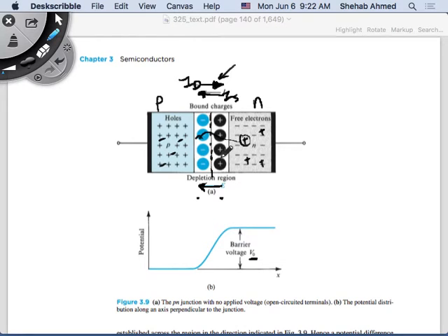And the potential difference. And hence, here positive bound charges, here negative bound charges. If you have two regions with a difference in charge, and an insulating medium between them, it's like having a capacitor. So basically, this graph is showing you when they're joining each other, that's the curve, and then when they're fully joined. Which graph? This curve. This one? Yeah. This is showing the fact that there is a voltage here. Yeah, but the voltage is changing because the holes are going to the electrons, right?